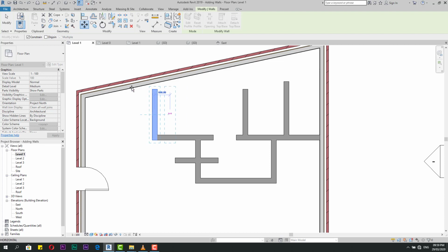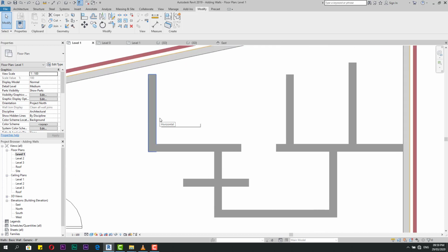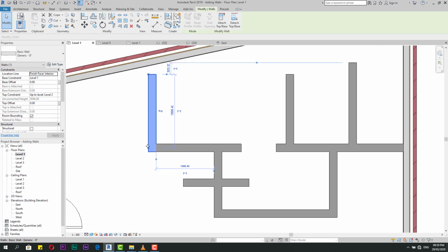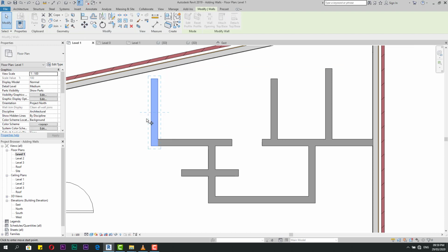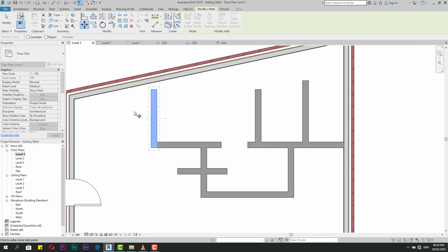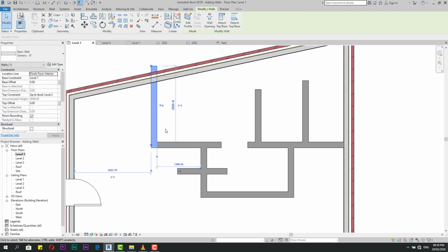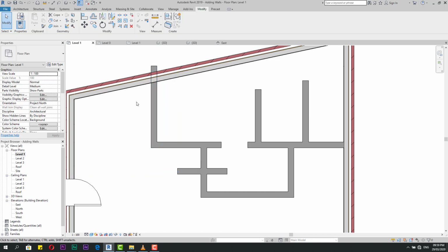The other thing I will uncheck is Join. What does it mean? Take care. We say that Revit is smart. When I make this wall and it is joined to this other wall, Revit understands, when you need to move this one from here up to here, what will happen: it fixes this point because it knows they must be joined, and then makes a stretch on the other one. I will press Ctrl Z.